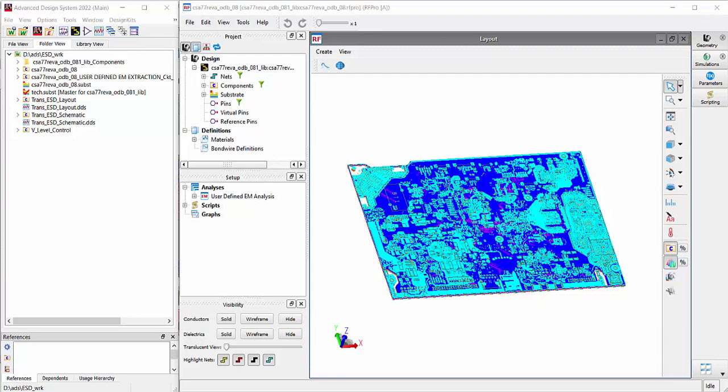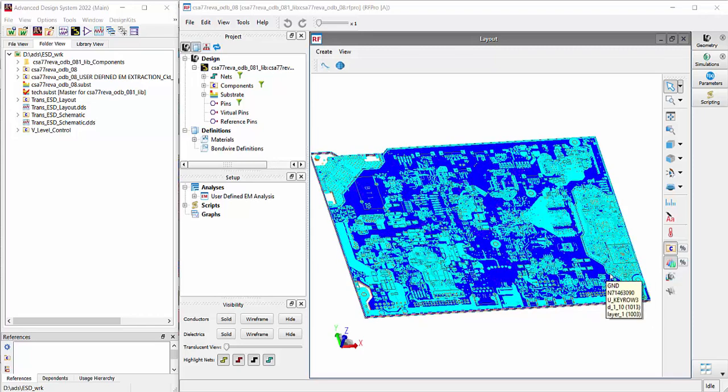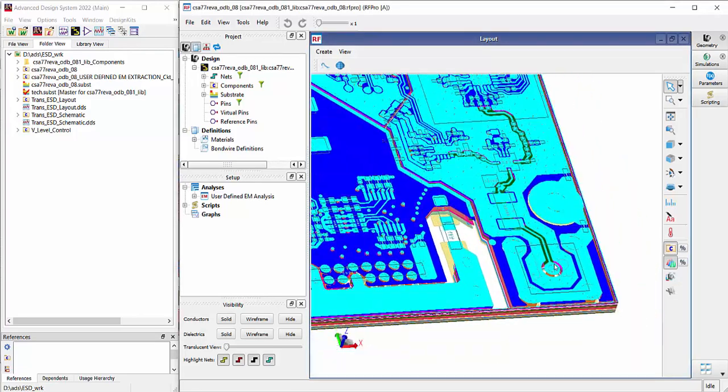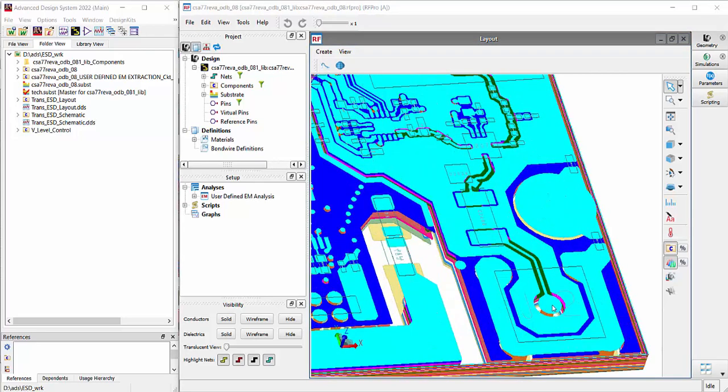This PCB is a COM Express module and can be mounted on any motherboard to have quick access to high computing power. To build an example, I searched for a connector and found on the lower right side an SMA connector. Here at the connector, I will apply the ESD pulse. Here's a capacitor, here's the ESD diode, and here's the chip. The goal is to protect this chip and all other electronics from a high electrostatic discharge pulse.